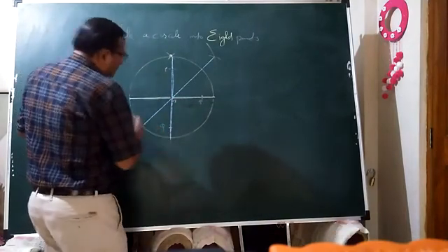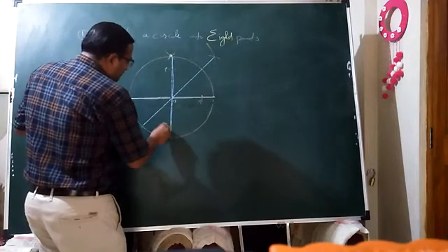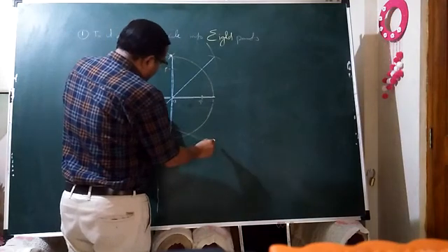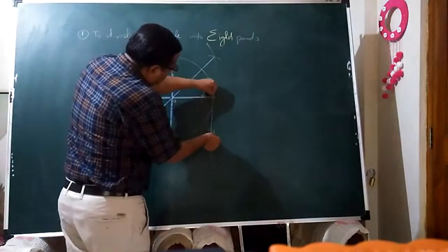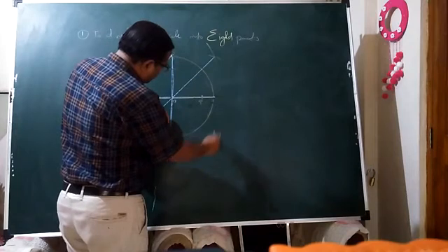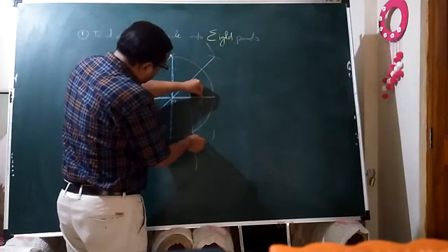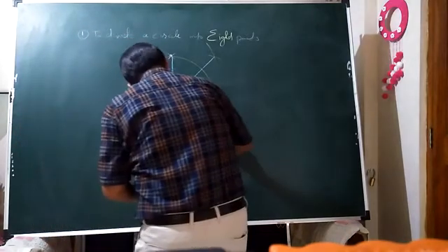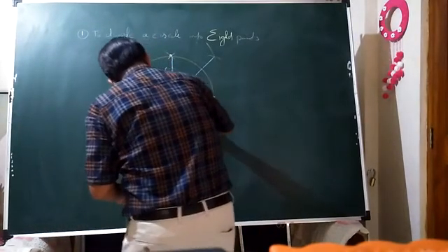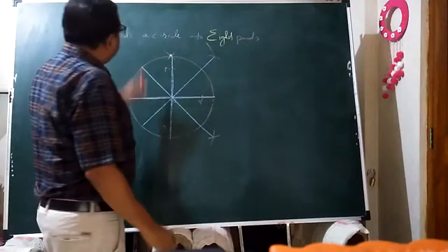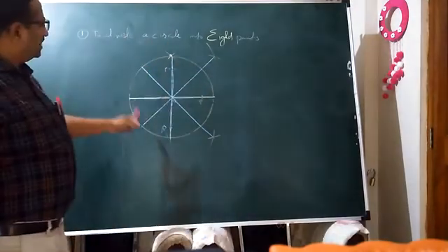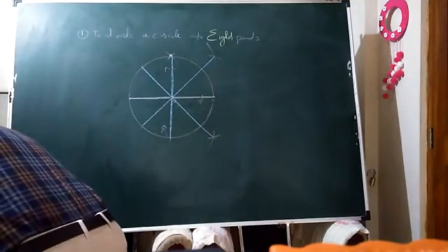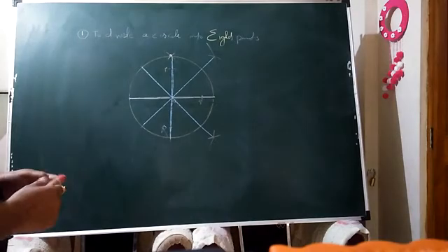So this is R. This is Q and this is R. Just like this procedure, repeat the same and get intersecting arcs, first from P and another from Q and R. This intersecting point you have to make pass through O in this way. So ultimately the desired solution of 8 equal parts of this circle we have got. So this is nothing but the circle division in 8 equal parts.